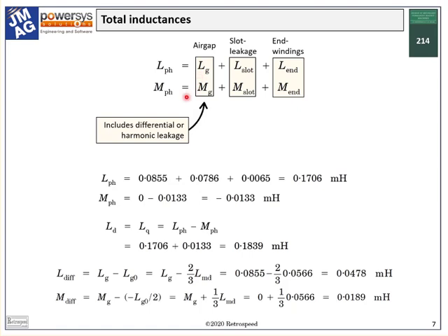The total LG includes all the space harmonic components, including any subharmonics whose pole number is less than 10. Also, where LG applies to one phase acting alone, LMD applies to all 3 phases acting together, and it's part of the classical theory that the component associated with one phase acting alone is 2/3 of this value.